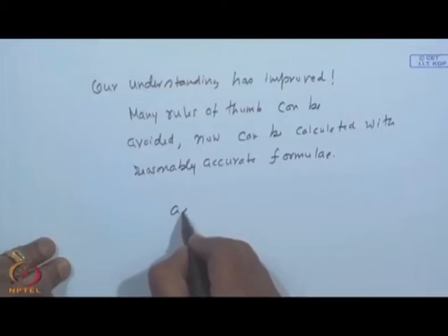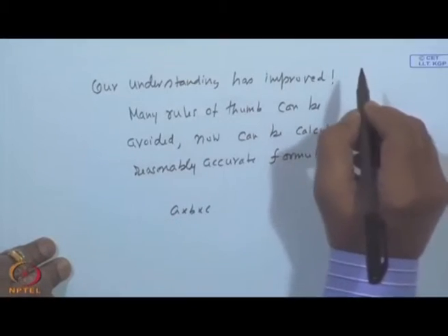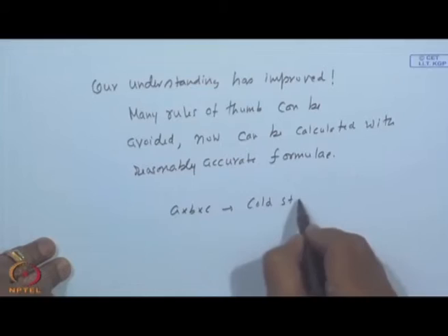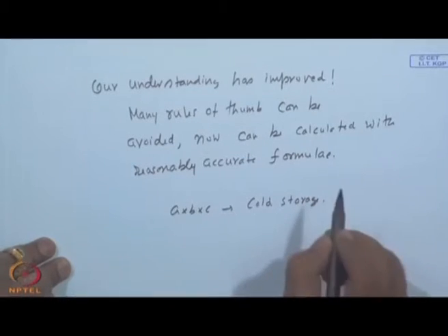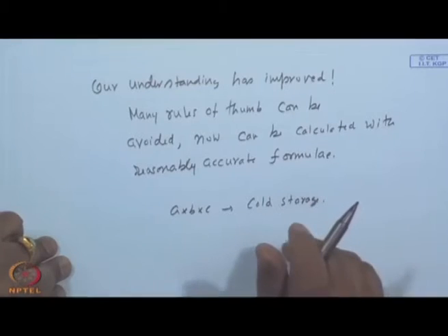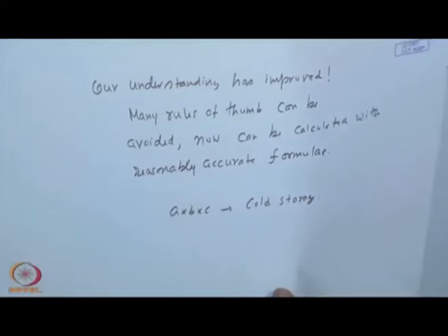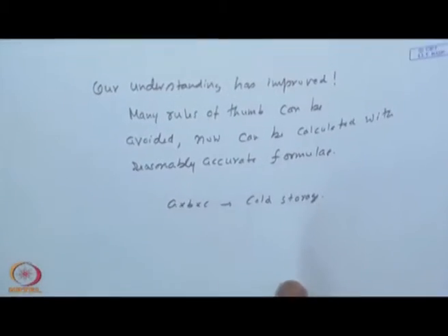Similarly, even if you consider a cold storage, you can choose a good orientation and A by B by C, or land area by the height ratio of a cold storage such that it receives the minimum solar radiation, subject to certain constraints like a certain height. You can play with A, B and what direction it sees, rather facing south, north, east or something else, and this may help in reducing the heat load on the structure, similarly on any other building.